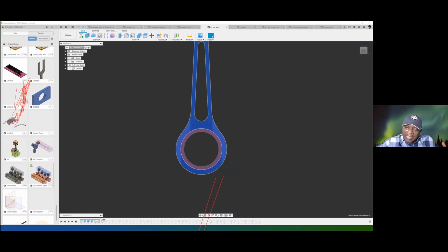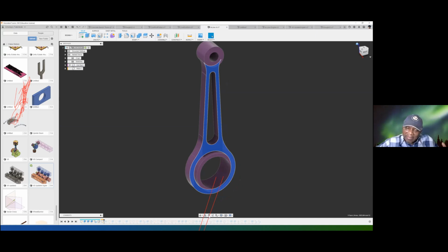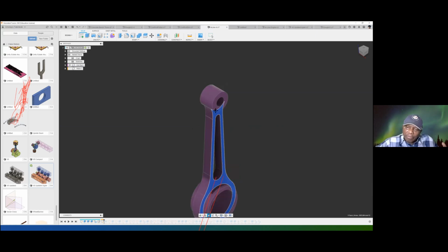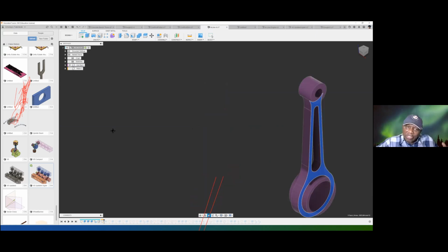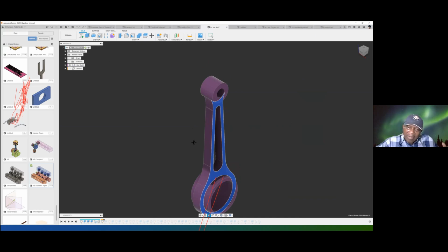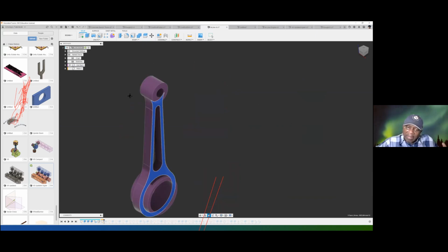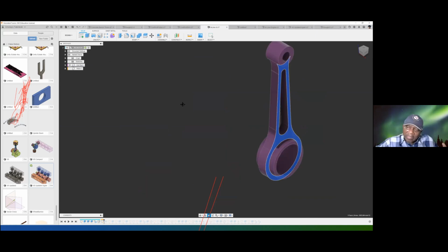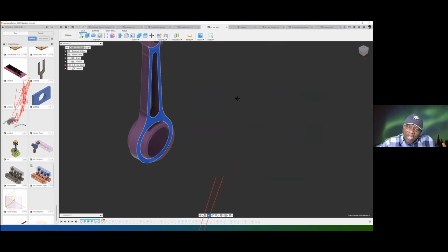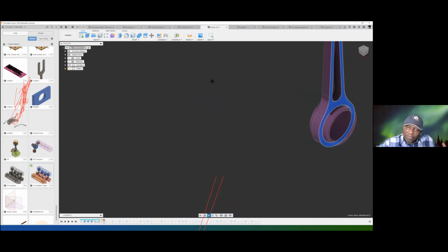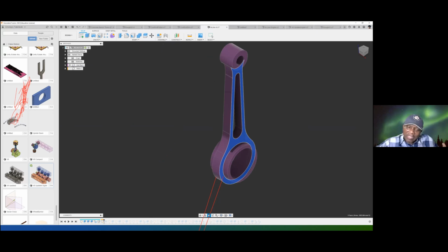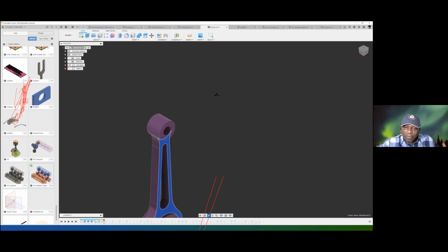Okay, now the next key there is pan. If you choose pan, you can move things, whereas orbit rotates, pan moves horizontally and vertically, and can pan to anywhere. This can be very useful when you want to look at a particular part of an object. For instance, if some part of it is hidden, you can just use pan to bring it out.